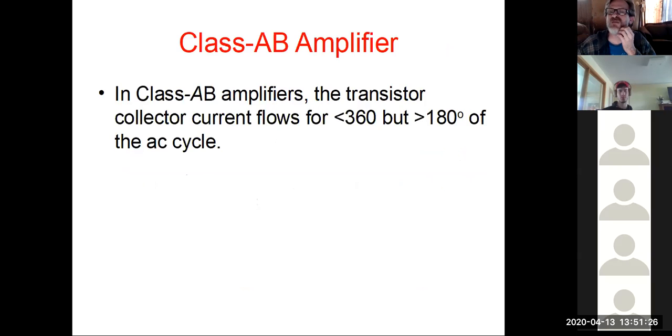And then we look at these. So this is like a hybrid one. We've seen that experience that crossover distortion with that final circuit there. So we try to incorporate some of the benefits of a Class A with some of the benefits of a Class B. And if you notice, in this case, we got like an in-between point. So we won't experience the full clipping like we did with the Class B, but at the same time, we don't get the full signal follow-through like we did with the Class A.